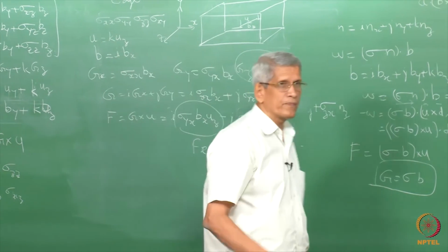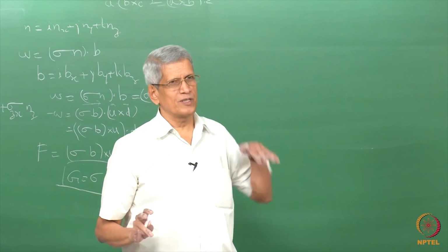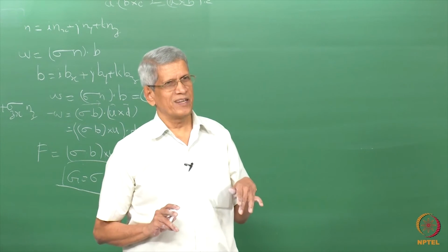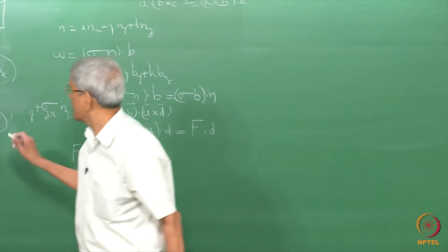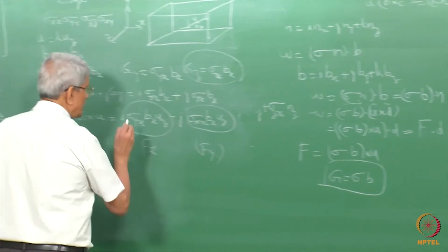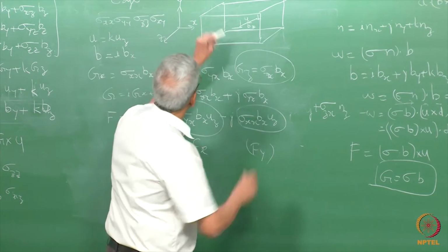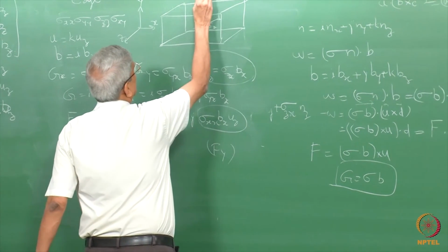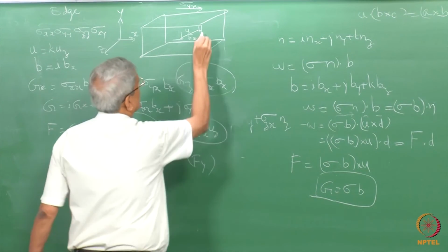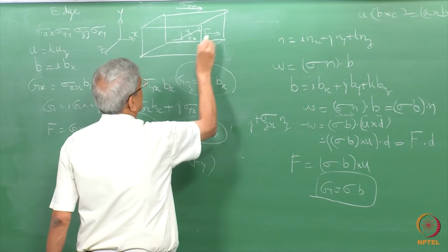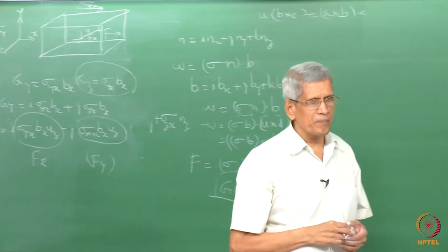That means that if we apply a stress, assume that we are applying only a shear stress in the xy direction, that is, on the y plane in the x direction, that is what this represents. This introduces a stress. What is the direction in which this is positive? We apply sigma yx. The Burgers vector is in this direction. The force will be acting in this direction. This becomes obvious from this expression.